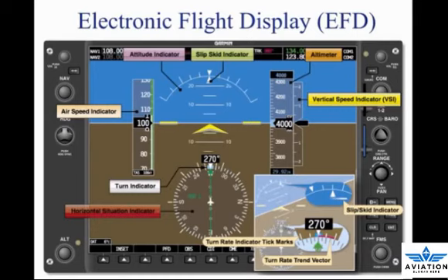The turn rate indicator is typically found directly above the rotating compass card. Tick marks to the left and right of the lubber line denote the turn, standard rate versus half standard rate. Typically denoted by a trend line, if the trend vector is extended to the second tick mark, the aircraft is in a standard rate turn.